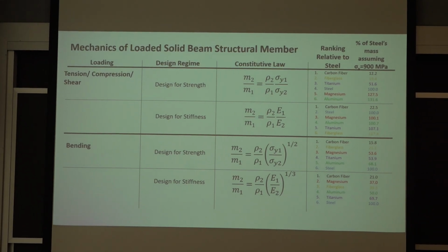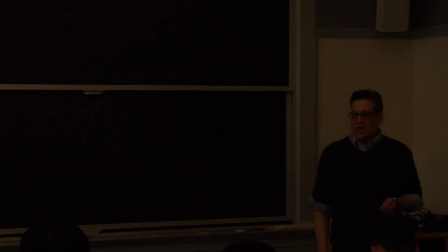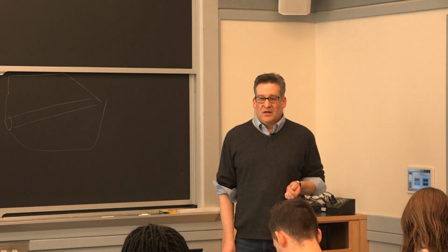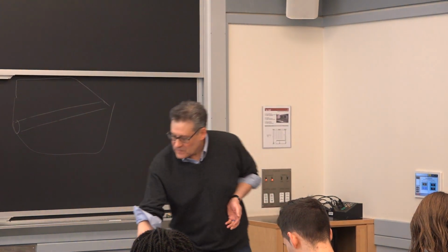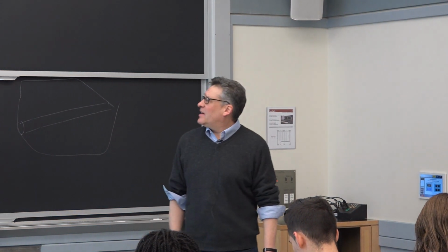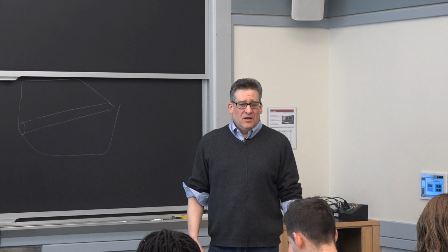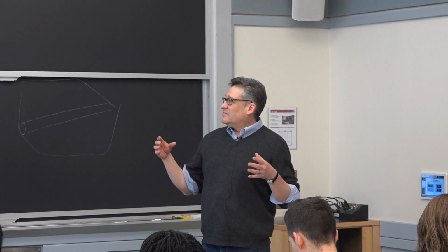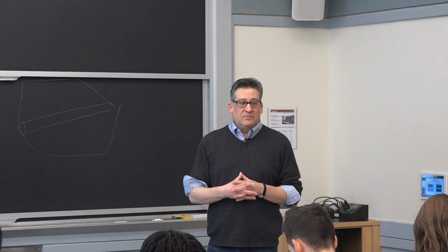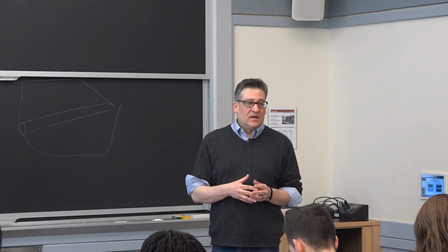And that's an intrinsic property of steel. It's really high, a 200 gigapascal Young's modulus, which is much higher than aluminum, which is like 70 gigapascals. So if you factor in that fact, you can begin to see the potential weight savings with aluminum, I'm sorry, with steel over those other materials.